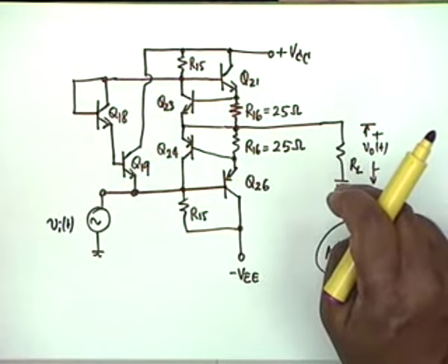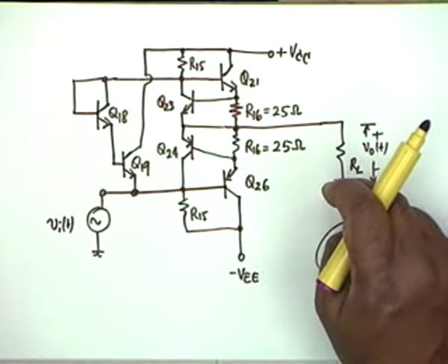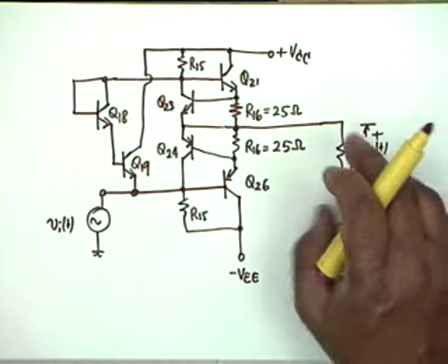Therefore Q21 will draw a large current and, we do not know what the VCC supply is, it might go into the breakdown region, or it might get so saturated that it is difficult for it to come out of saturation. Saturation means charge accumulation, and the charge requires a long time to come out of saturation.